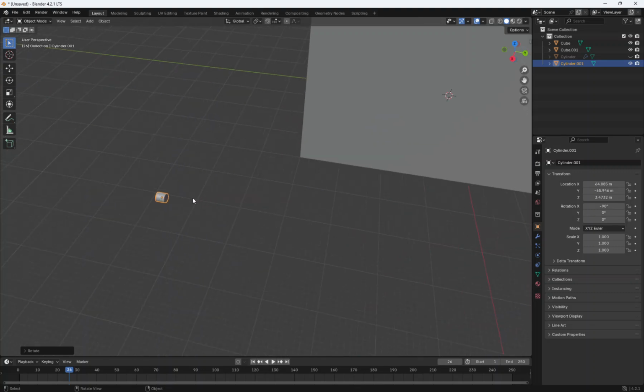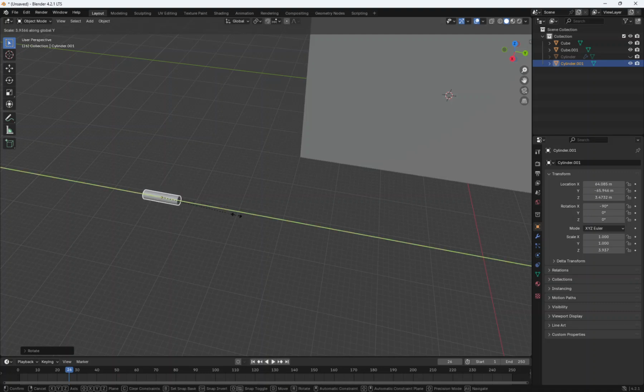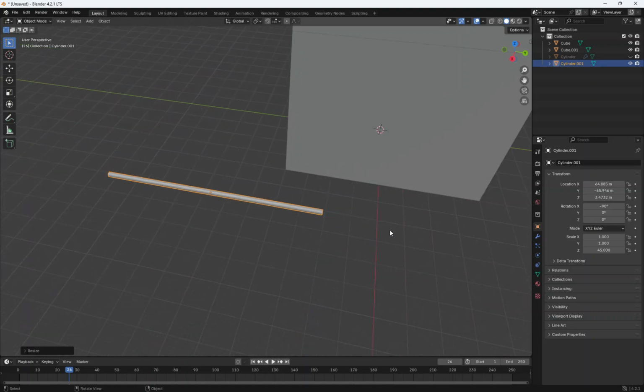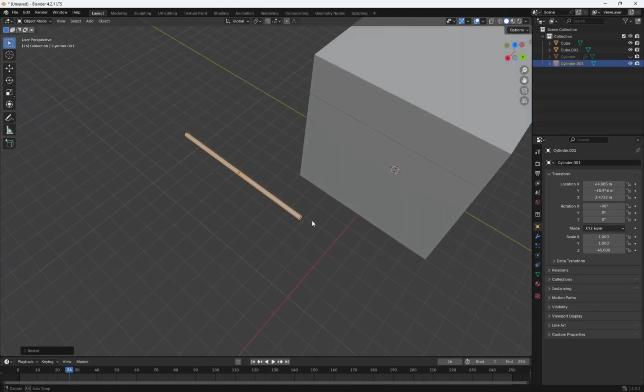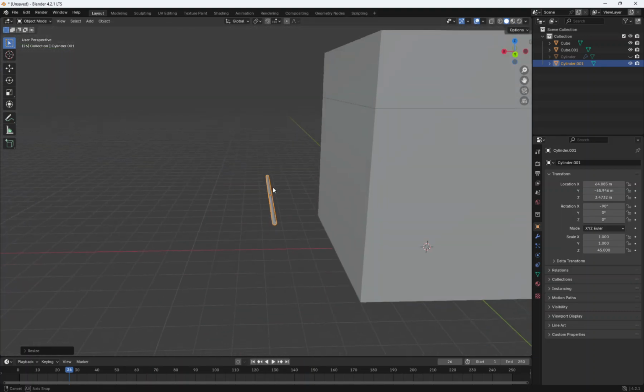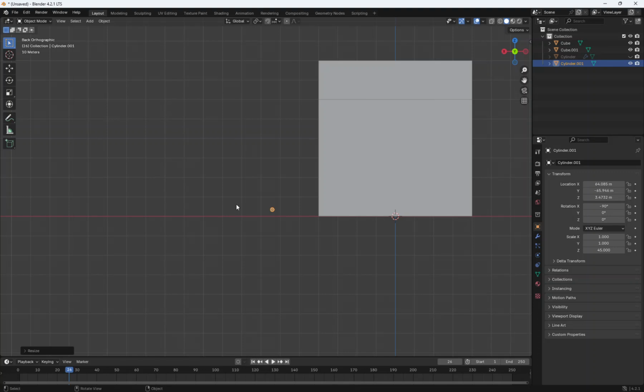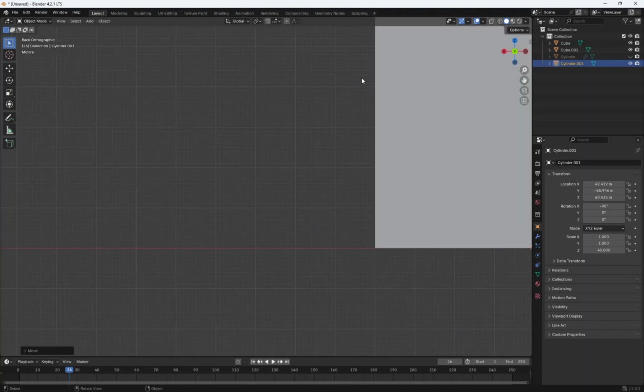So now I want to scale this also, so I'm going to press the S key, and I only want to scale it in the Y axis, so I press Y, and we can see that one's scaling up here, so I want to change that to, we'll say 45, because this one's just for reference. So I can pick whatever I want. And then I'm going to go to the Y view and press G again and get this close to where I want it up here.